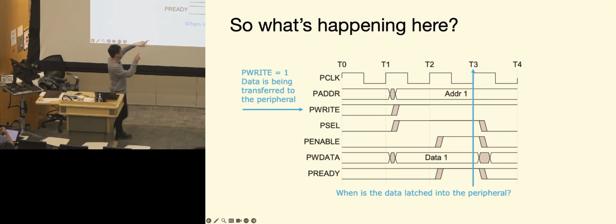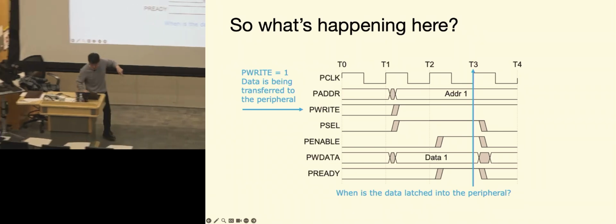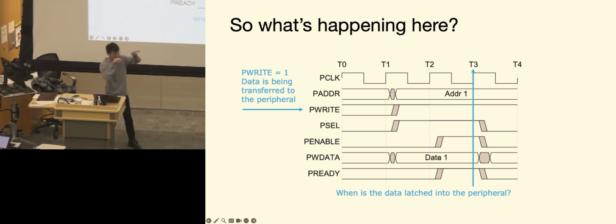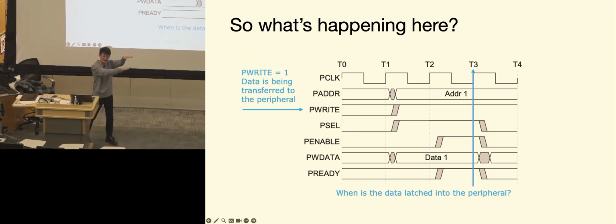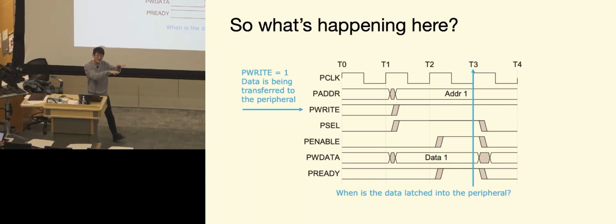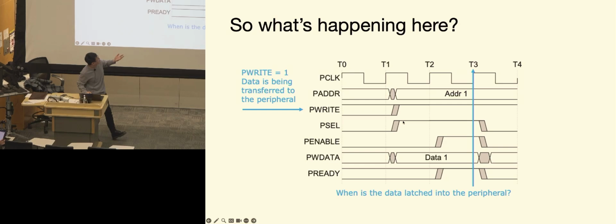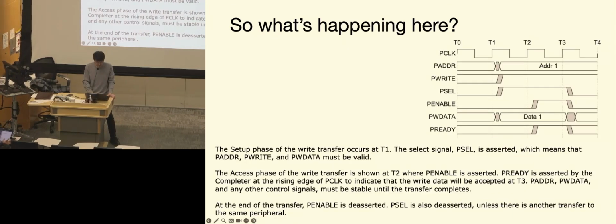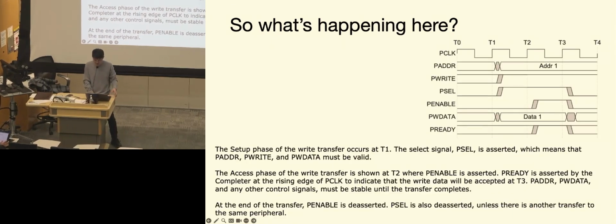And you will notice that sometimes, for example here, when the signal does a little cross across the whole thing, that usually means there are multiple wires, so it's very hard to represent whether it's high or low in that whole stage. But for those with just one wire, for example the P-select, it starts low and then becomes high, so you can kind of tell from that how many wires are in there. So yeah, we talked about this.